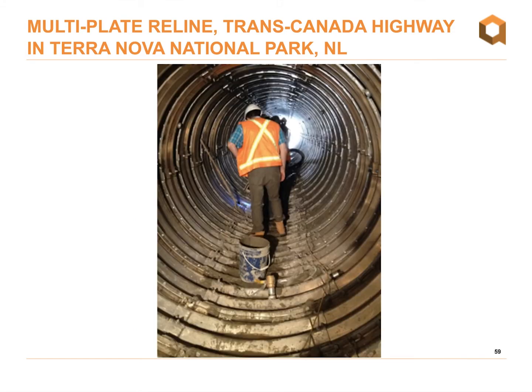So basically, as an overview of the project, there was a 10-inch pump that was placed at the upstream end, and water was pumped around the site, which allowed the multiplate to be dewatered. The existing multiplate had to be, of course, first cleaned of debris and rocks. Plates were placed in bundles at the upstream end of the structure using an excavator, and then were brought into the structure by hand by the crew.